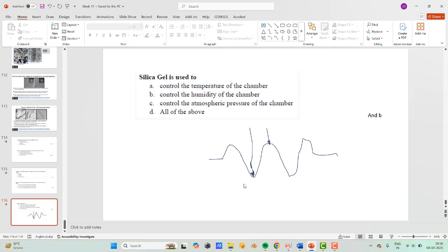Normally in SEM, we get the surface information only. We are not getting it from the bulk. If you want to check the bulk information, then we have to cut the cross section, and then we will get the image of the bulk. So this is mostly from the surface, but you are asking about the depth of penetration. There might be a formula for this, but I'm not sure. I have to check the depth of penetration. Right now I can think of this only.